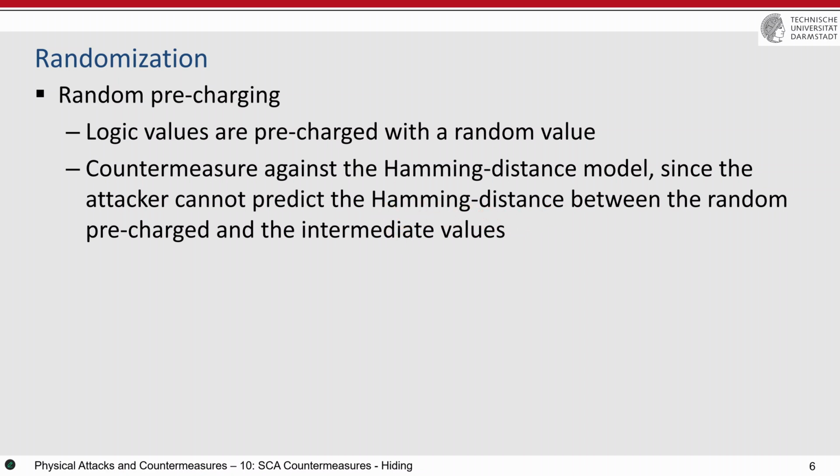But of course, it has some disadvantages, meaning that it has some overhead in your implementation. Because, for example, you run the AES every clock cycle, and then the registers which are storing something, every clock cycle you want to first write a random value into the register, and then, for example, an S-box input comes to the register. What happens is every 2 clock cycles you have your AES. Or you make a pipeline implementation.